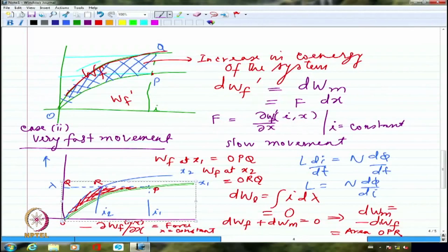Lambda multiplied by the reluctance. Reluctance has decreased. Lambda has remained the same. So lambda multiplied by reluctance is MMF. MMF has decreased. In the first case, MMF has remained probably the same, whatever, but here the MMF very clearly has decreased. Right?